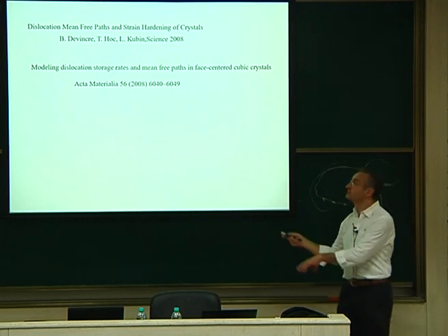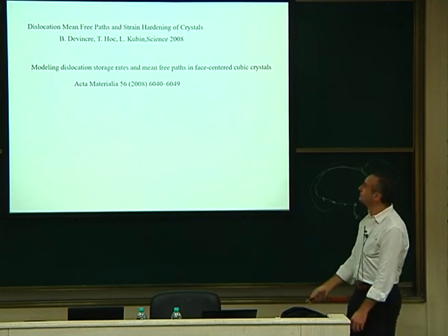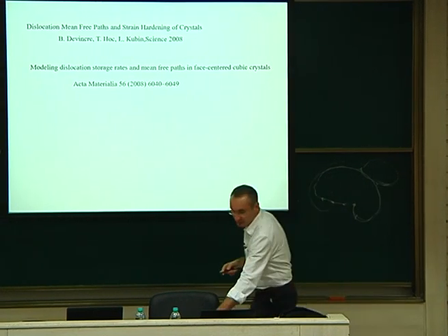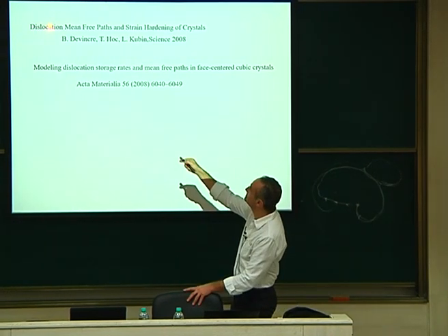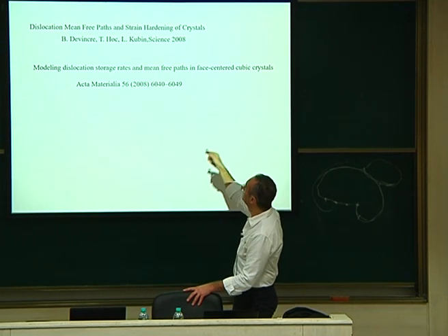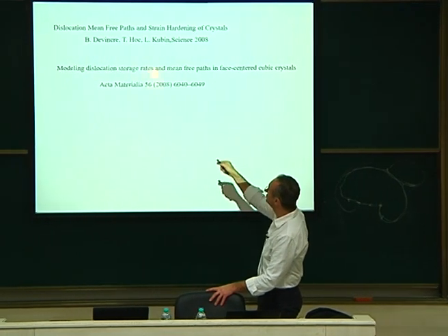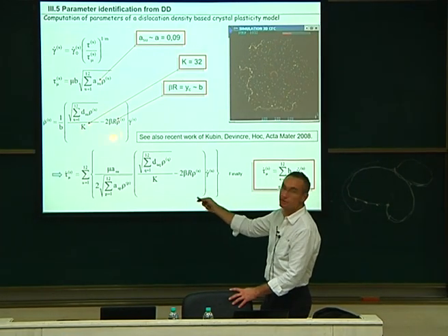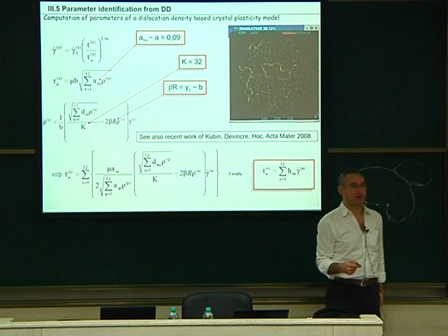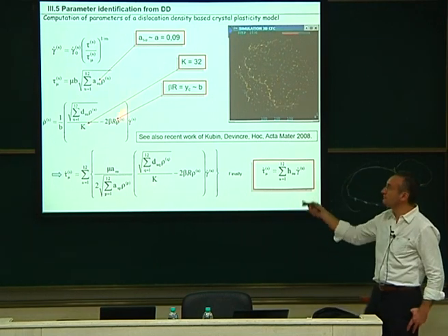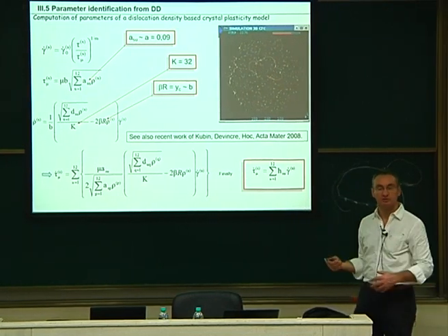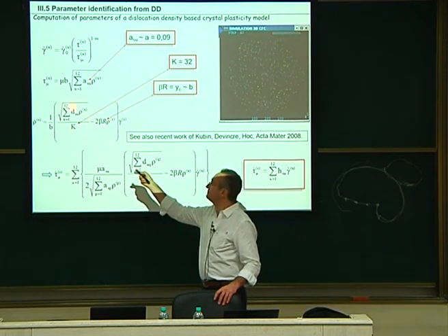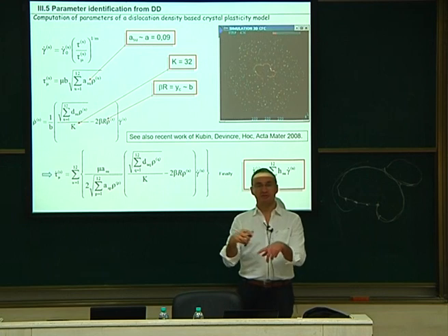The idea is the same. I cannot write down the equation because of this stupid computer, but what they change is this thing. Typically, it concerns the dislocation mean free path and the strain hardening. This is the same dislocation storage. So what did they do? They just changed this expression here. So in this paper, they improved this formula a bit. It's just an improvement, not a big change. It's an improvement where they take into account in that mean free path all the different types of junctions.